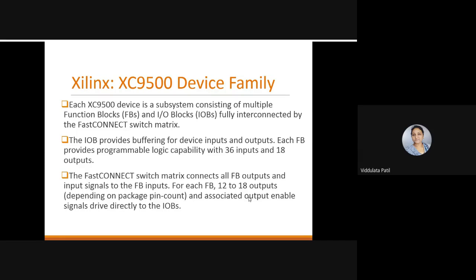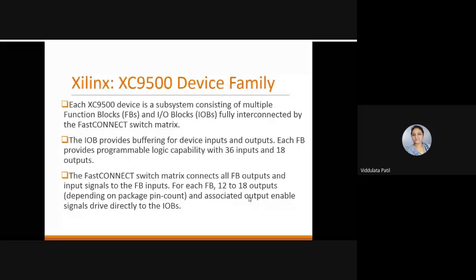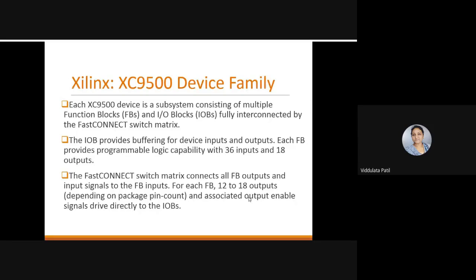The IOB provides buffering for device inputs and outputs. Each FB provides programmable logic capability with 36 inputs and 18 outputs. And the fast connect switch matrix connects all FB outputs and input signals to the FB inputs.